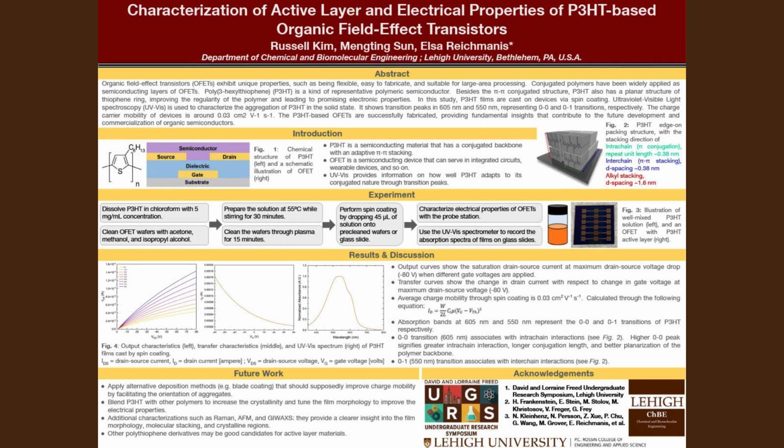For the last 1.5 years, I've been working with Professor Elsa Rekmanis and her graduate student, Mongting Sun, to study the charge transfer properties of an organic semiconductor. And right now, I'd like to present my poster, which is characterization of active layer and electrical properties of P3HT-based organic field effect transistors. So, to break it down, there's P3HT, which is poly-3-hexylthiophene, and OFET, which is an organic field effect transistor. P3HT is basically a representative polymeric semiconductor.